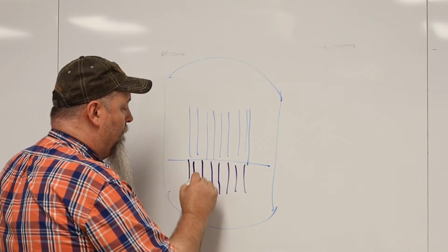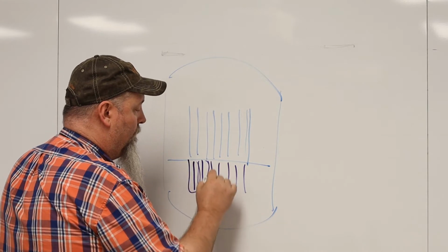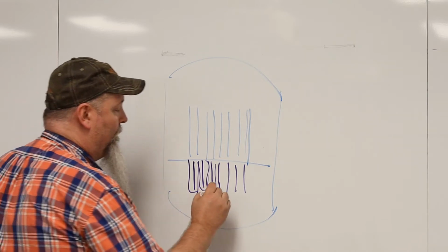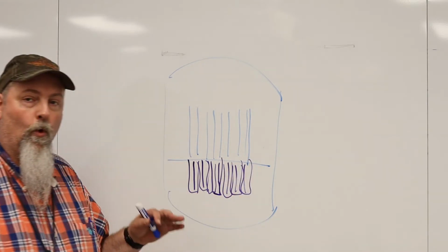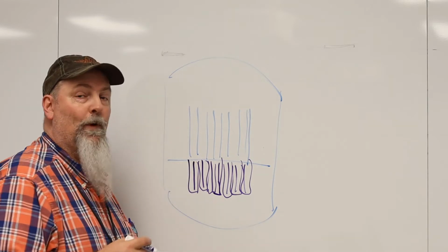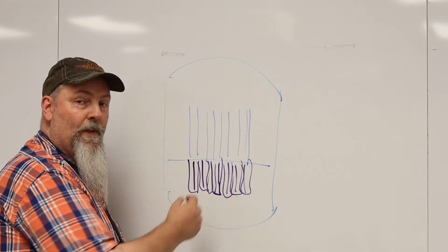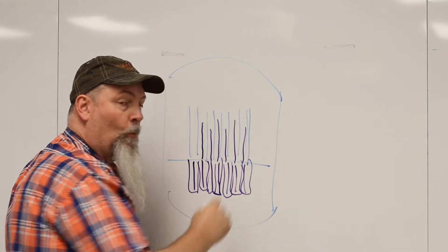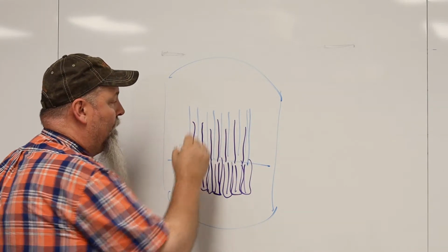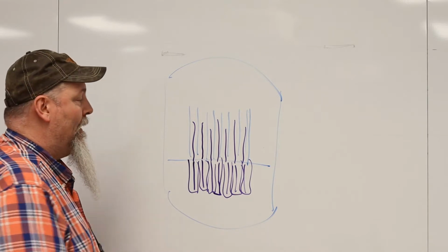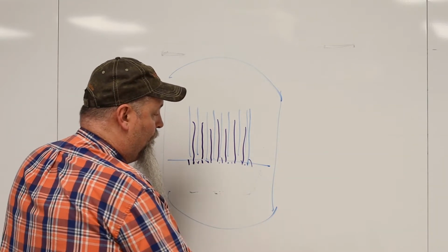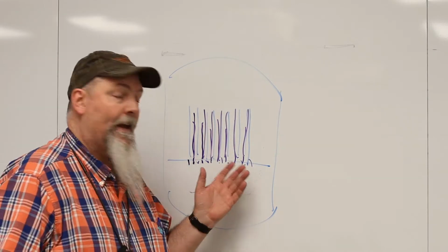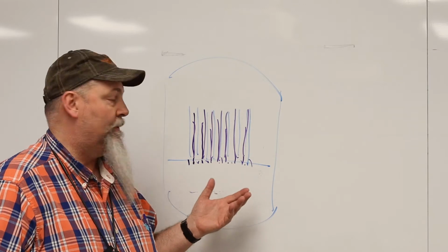And they have tubes that allow us to hydraulically drive them into the core to control reactor power. If we need to raise power, we withdraw them, and as we need to lower power, we insert them into the core. And then, of course, on a reactor scram, they insert fully into the core. And a reactor scram is one of our automatic protective features.